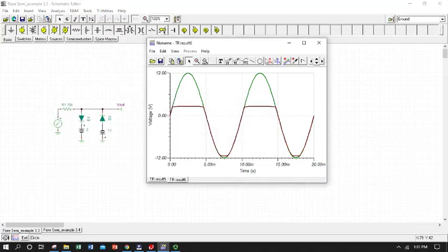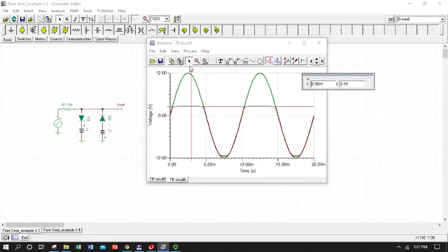Aha! It's looking good on the negative end. And here we go, 2.55. So that's 2 volts and something, just shy of what we would expect from the forward bias voltage. These diodes seem to have a forward bias voltage of about 0.5 to 0.6. And we've known from reading some diode spec sheets that forward bias voltage can vary. We typically use 0.7 as a baseline. And as expected, we're getting pretty close to 12, 11.42 down here at the bottom.